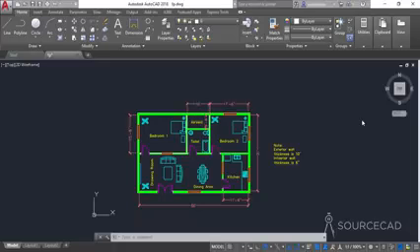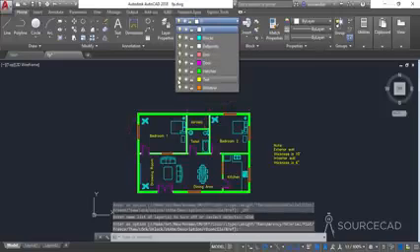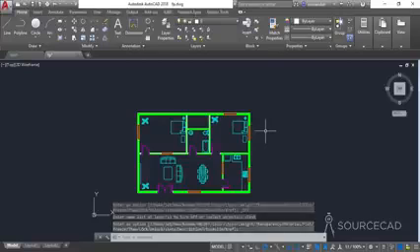So here we have this floor plan and we have the dimensions, text and rest of these objects. For making the elevation, we actually don't need all of these distractions. We can hide these objects, and if required, we can bring them back later on. Now in this case, I'll use the front elevation. So this will be the elevation which we'll make. For that, I'll first start by hiding these dimensions and text. I can simply do that by hiding the layer. So here we have this text layer and the dim layer. Let's click on this light bulb icon here as well as on text. That will hide both of these objects.